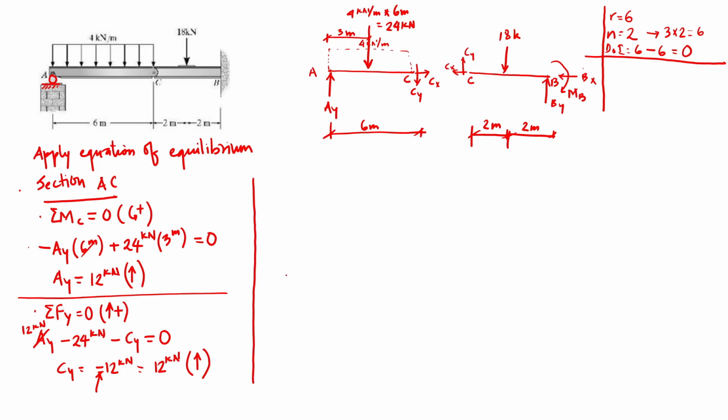So this is 12 kilonewtons. This means this is incorrect. This would actually be going upward, CY. So this equal and opposite will be transferred to section CB, which is CY. There would not be any confusion when you calculate some moments at this section to carry over negative, because if you forget to carry over this negative toward that calculation, you might make a mistake.